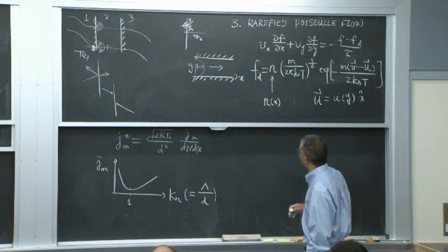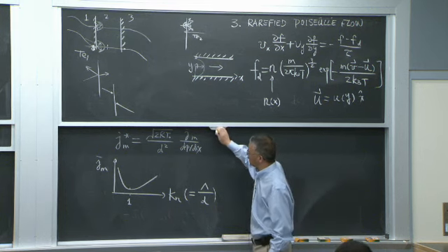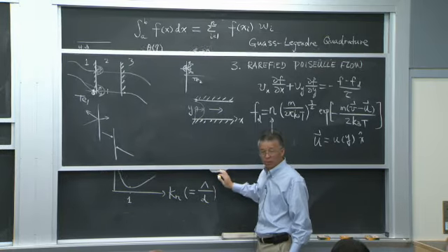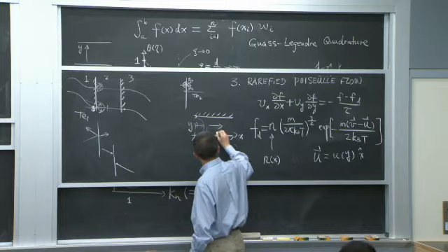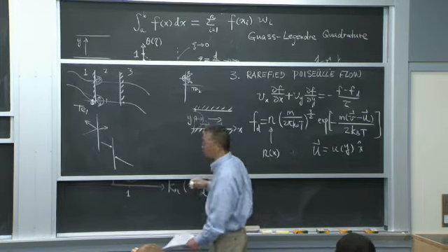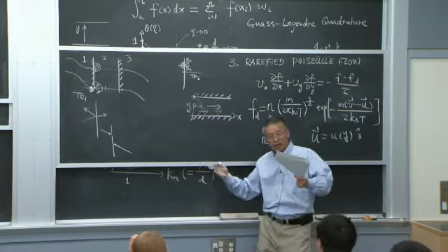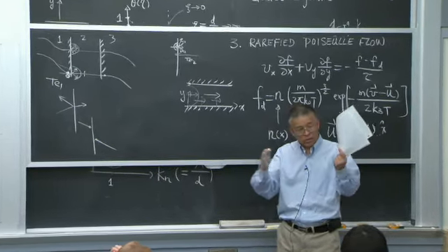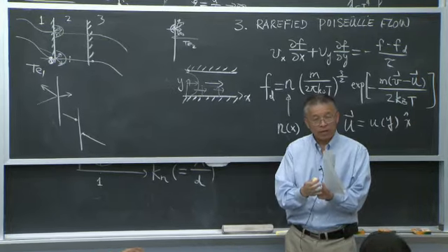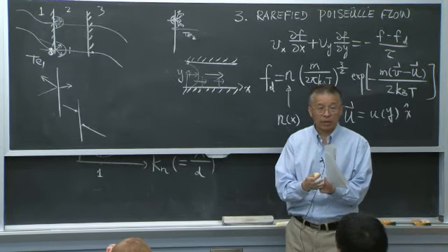And the reason for this, I try to come up with a very direct picture, right? And the reason is this. You have a pressure-driven flux going in the x direction. And we see in heat conduction, roughness always decreases the thermal conductivity, right?